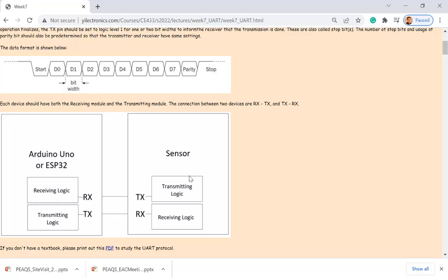That's incorrect because they must have a VDD and ground inside, right? There are all these transistors and digital blocks. They are powered and grounded. However, for the communication, you only need 2 pins, 2 wires. It's a single bit for each wire.